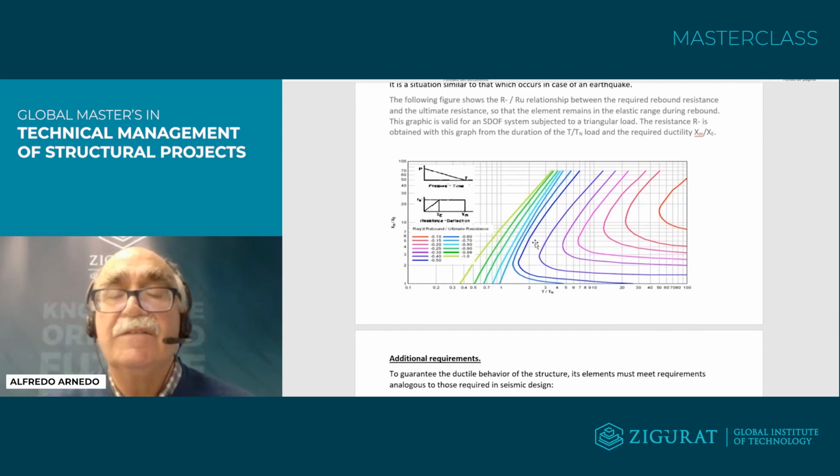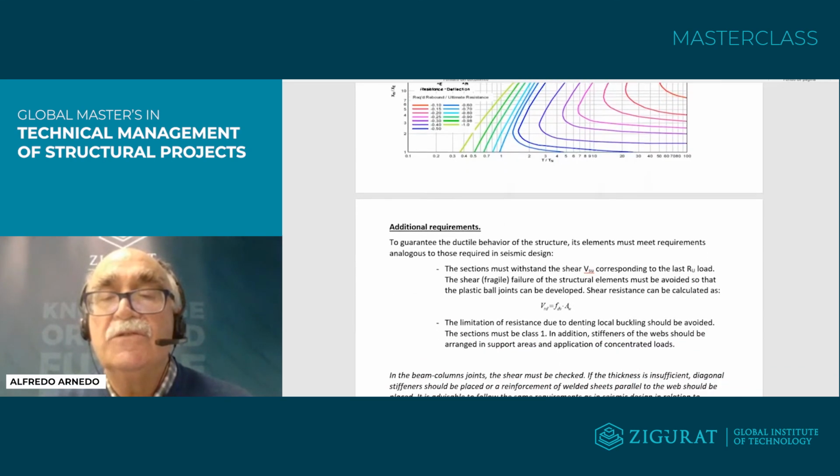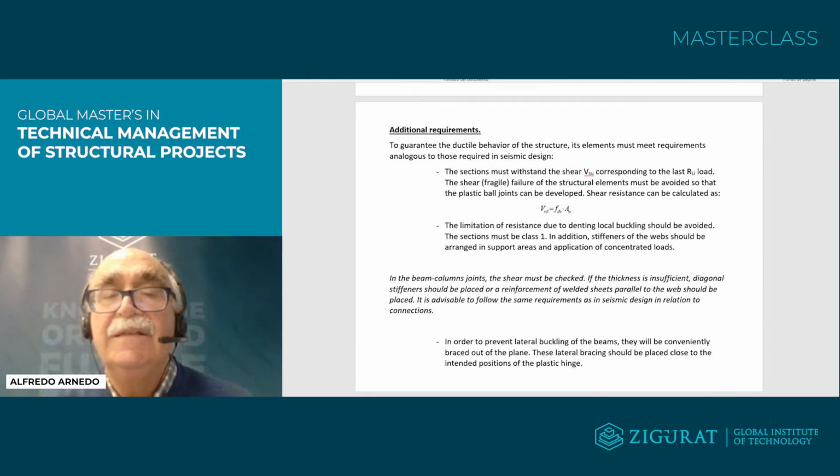The steel structure has to be prepared, depending on the duration of the force in relation with the period of the structure and the duration of the phenomenon to reach different values. So this is important to consider, especially when we design the connection. The connection has to be prepared to act in both directions.